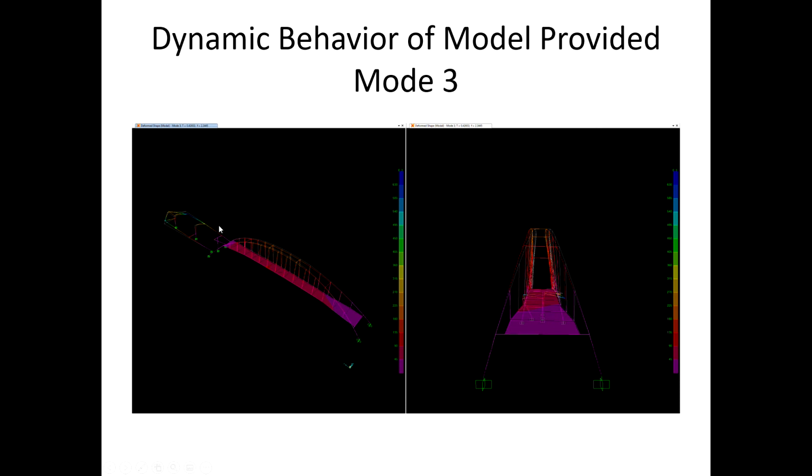And this is important, these sets of modes, because we suspect that some of the biggest problems in the existing finite element model have to do with the connection between this part and this part. There's an expansion joint here that's tricky to model. And this part is especially wobbly. So we'll pay attention to that.